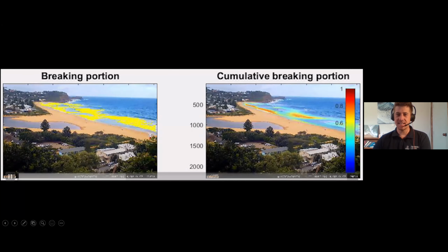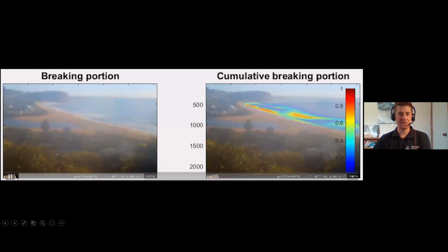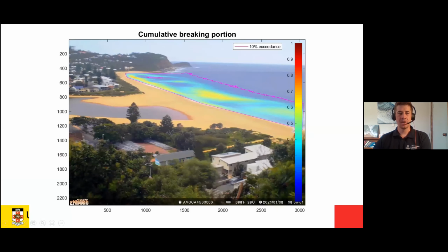And you can start to see this intensity plot of where wave breaking is occurring. You can see a couple of interesting things if we zoom in on this wave breaking intensity map. Using Tom's tool, you get a nice little map like this where you can look at areas where there is no wave breaking. In these areas, the absence of wave breaking, you can infer that there are likely to be rip currents. You can also look at where the sandbank might be, based on where there's a lot of wave breaking. So these are quite useful tools in understanding coastal morphology.